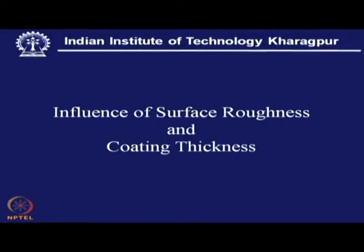So, this is one important area to be dealt with, and at the same time we see the thickness of the coating. Now, what should be the order of thickness, whether it is just 1 to 2 micron or several tens of micron or several hundreds of micron. This has to be judged considering the substrate coating relation, their interface, deposition condition, particularly the deposition temperature, interfacial stress, then interfacial reaction layer, and there are many other issues which actually decide what should be the order of coating. But applying our common sense, we understand that when it is a wear resistant coating, durability and thickness have some kind of correlation.